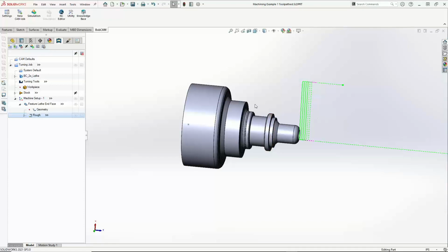Pretty much the rule of thumb I follow, the best rule of thumb I've come up with for when to save, is when you finish calculating a toolpath. Calculate your toolpath, save. And then before you launch your simulation, save. During calculations and during simulation loads are the two times that my computer sometimes struggles.